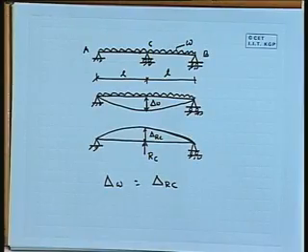Some of the cases we have derived, some of the cases anytime we can derive with our basic understanding in the form of differential equation technique or moment area theorem, or we can just consult some standard table, from there we can pick up. So, what will be this value? Omega L will be your 5 omega L to the power 4 divided by 384 EI.